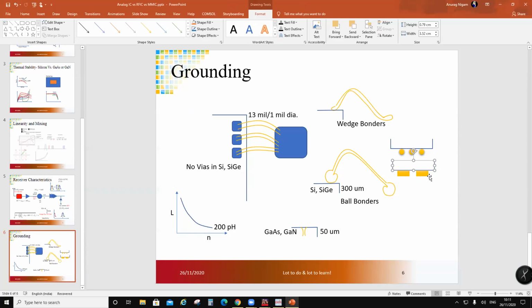Okay, so this is tin only. Lead is not allowed because you will not clear the specification. It has to be lead free. So if this is tin, then what they do is put a cap around these balls or around this slab, so that even if it melts and floats, the cap is going to restrain the molten tin. Okay, so this thing sits there.